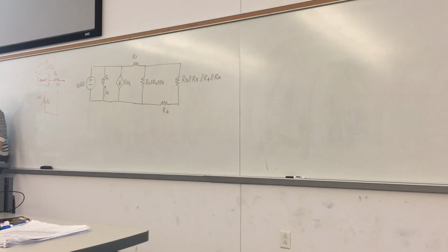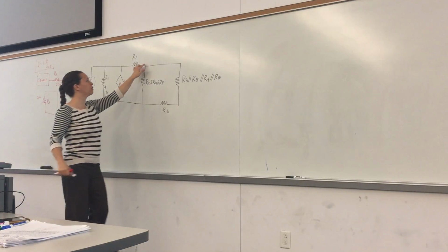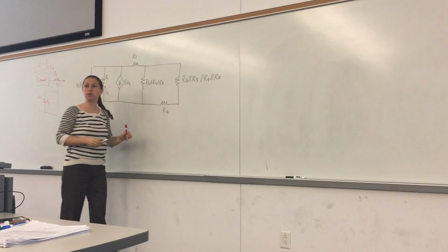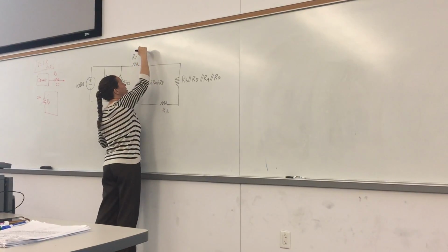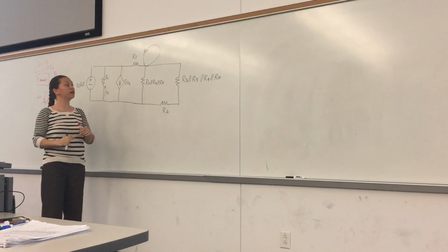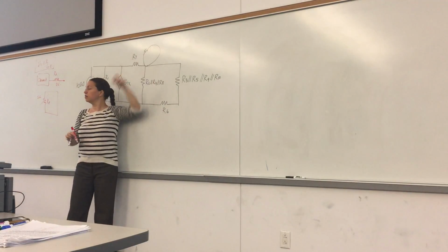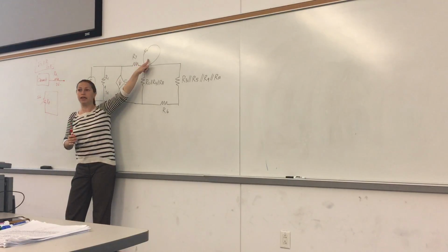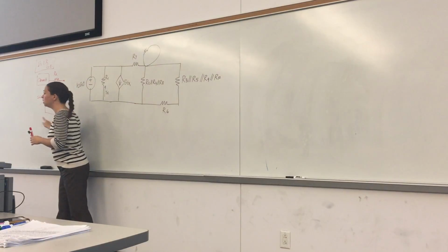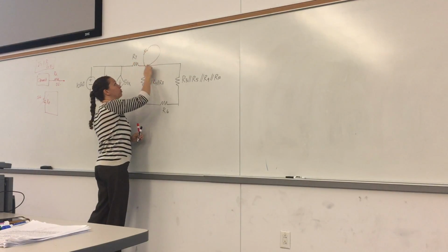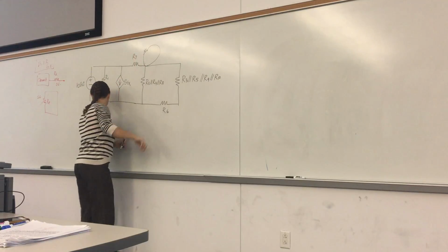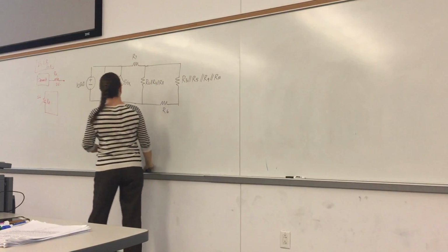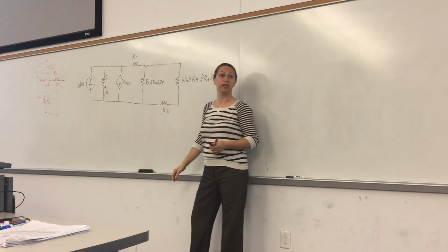Okay? Now, for that resistor that we had over here, we had actually 3 resistors in series with each other, which makes it like a single resistor like that, right? Now, if you look over here, in this case, which one is that? Is the situation Rx or Ry? Ry. That's like Ry, right? It's like Ry that's in parallel with a wire. It's this resistor in parallel with a wire. That's why that's gone. That's irrelevant to our solution, a dummy resistor, and doesn't have anything to do with the solution. That's why we ignored that. That's where we stopped, I think.